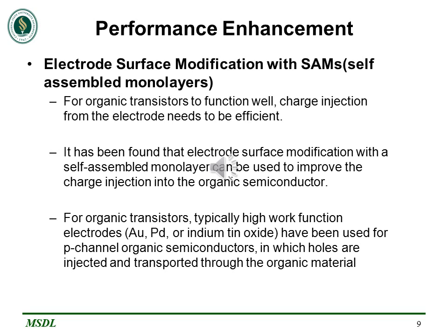This requires the work function of the electrode to match well with the energy level of the organic semiconductor, such that the energy barrier for the charge injection is low, so that we can transport a charge within the semiconductor and the organic transistors at a high pace.